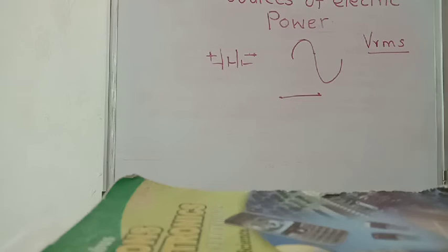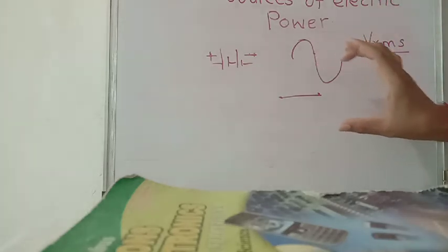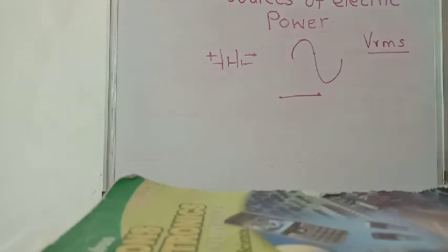So the transformer changes the voltage level from 230 V to our requirement. Generally a step down type transformer is used. If we want 9 volt DC, then we use a 9 volt secondary transformer. Its secondary voltage is 9 volt 500 milliampere, or 300 milliampere.